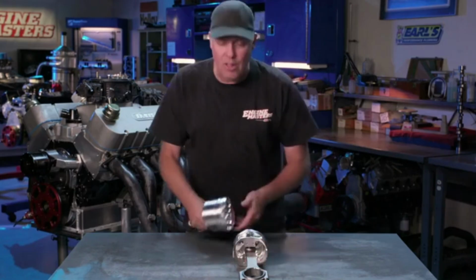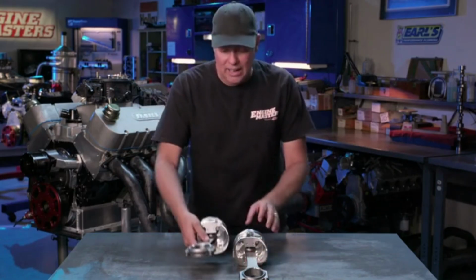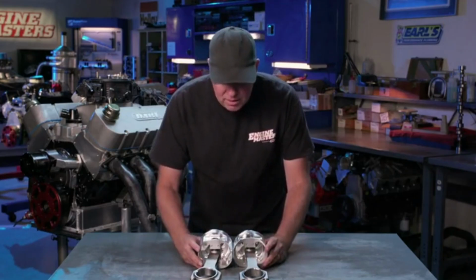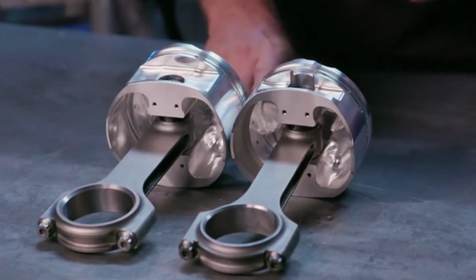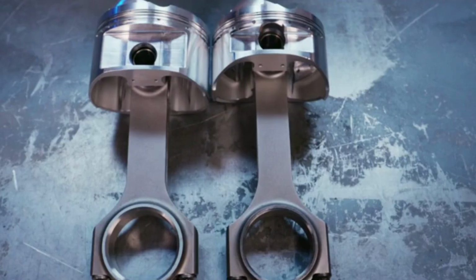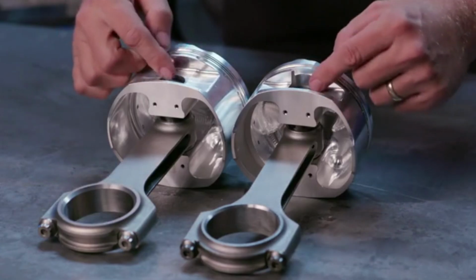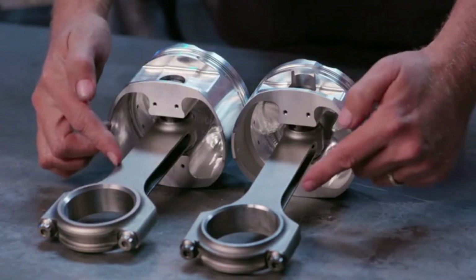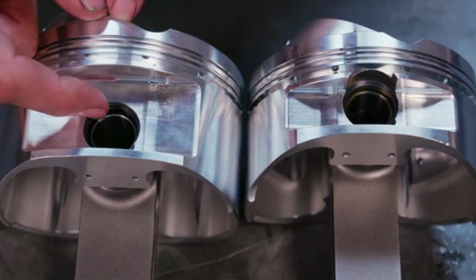The other thing that we need to look at here, and this is another aspect of connecting rod length, is if I put these side by side and line them up exactly at the top of the flat surface of the piston, not at the top of the dome, you can see that the compression height of these two pistons is very different, because in order to package between the stroke of the crankshaft and the deck height of the engine, you have got to offset the compression height of the piston to accommodate the length of the rod. So you can see here with the short rod, I've got a very tall piston compression height.